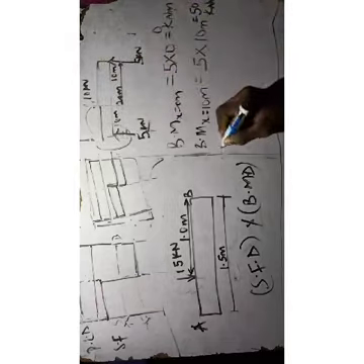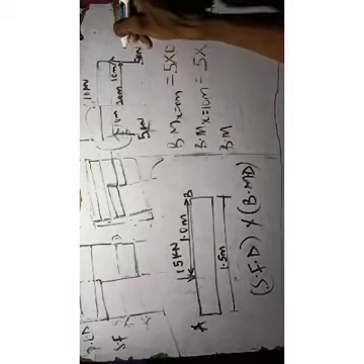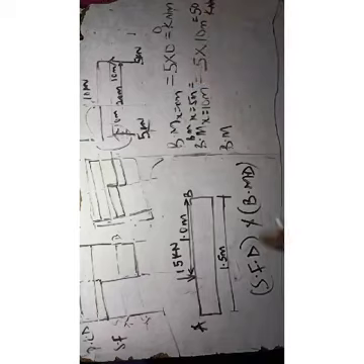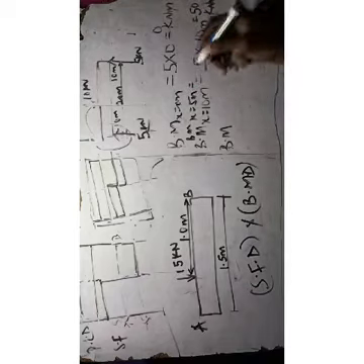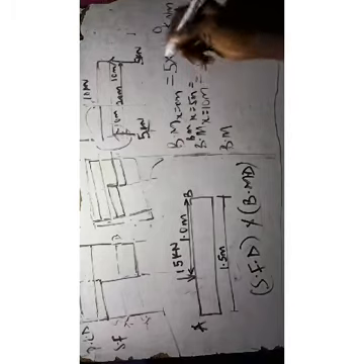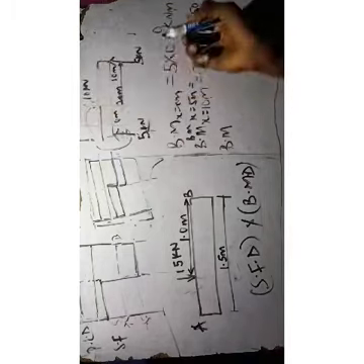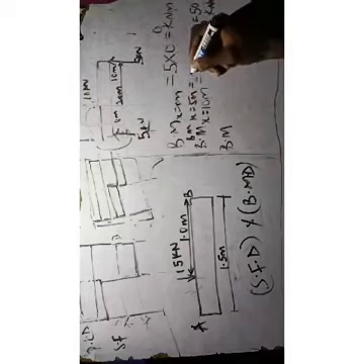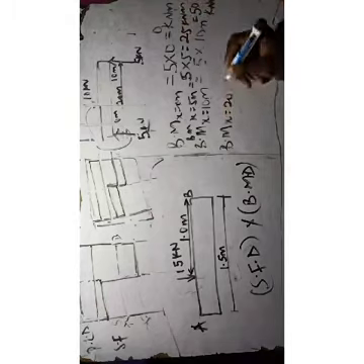Next one, the bending moment when x equals what? You can take the bending moment when x equals 5. Okay, let me show you a sample. Let's say bending moment when x equals 5. It should be on a straight line, not curved, rather slanted, diagonal. So when x equals 5, you just section it when x equals 5. Yeah, you are cutting it. And that will be equal to this 5. When x equals 5, the distance is 5 meter. That will be 25 kilonewton meter.